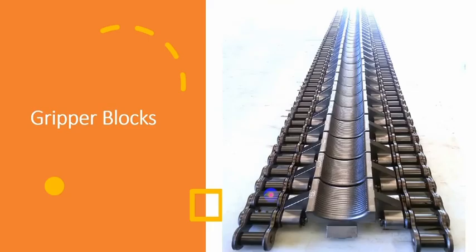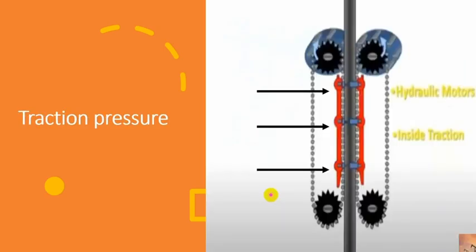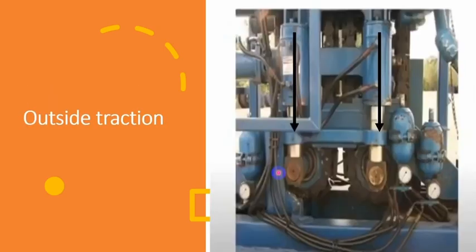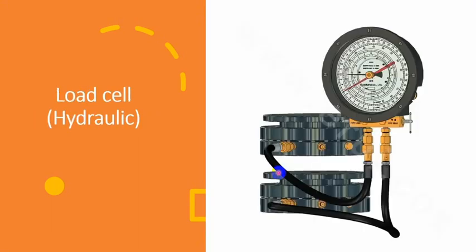So if our system is hydraulically measuring weight, we can have two load cells, one for tension and one for compression. And this is the image of a hydraulic load cell. We have a piston here pushing against a diaphragm, and this diaphragm pushes against hydraulic oil pressurized in this hose up to this weight indicator.